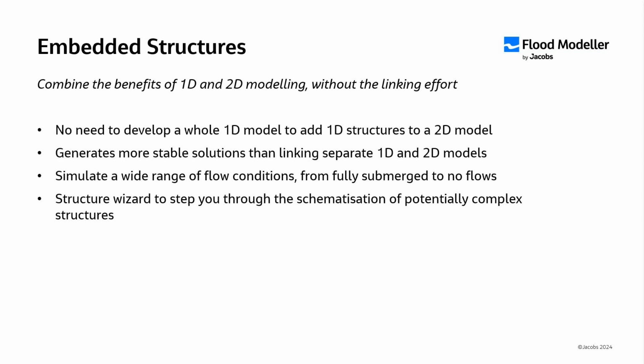Maybe you have, in the case I'm going to show you in the demo, a culvert through an embankment, or through the embankment I just showed you. If you imagine trying to build a 1D model of that, it's such a small feature. You build a separate 1D model, a separate 2D model, and link the two together. Quite frankly, it's a bit of a faff. It's a bit of a pain to do that, and you have to draw link lines and all that kind of thing. It gets a bit laborious for such a simple feature.